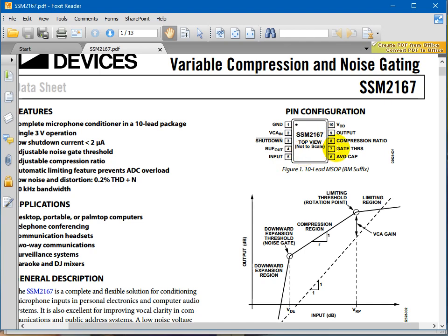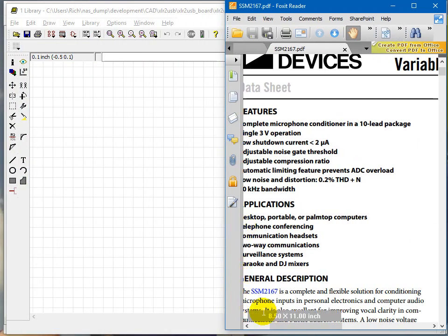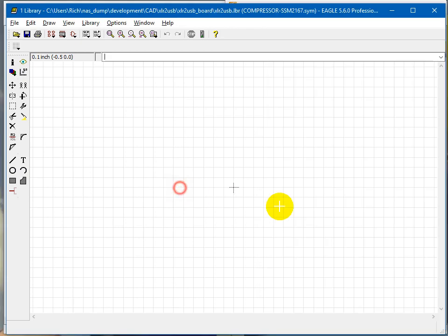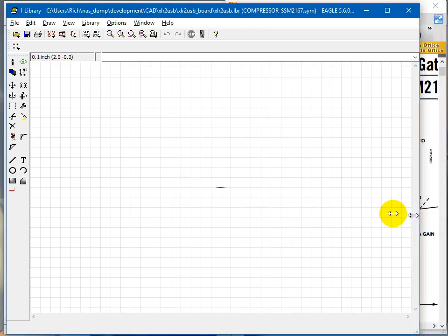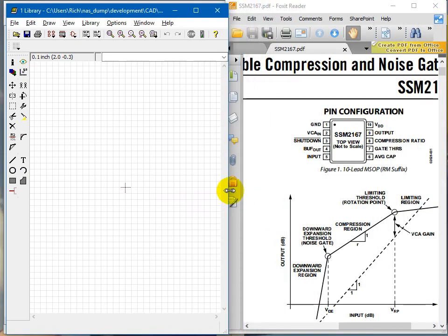I particularly like to see schematics, and when I read a schematic, I would like to get to the point, right? So organizing the information in a schematic is important to me, and so I will reorganize these pins in a way that makes the schematic flow better. That's just me, because most of the time I'm the one who has to deal with my schematics. So I'm going to try to get both of these on the screen at the same time, because one of the first phases that I will have to deal with is making sure all the pins are actually present and accounted for.